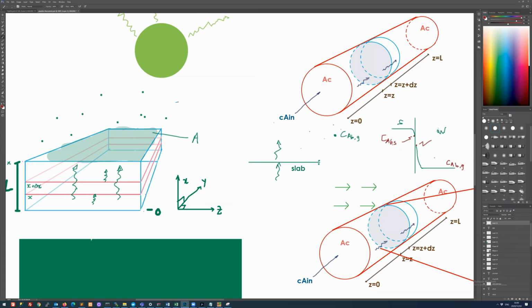And by the way, of course, if your air is well enough mixed, so for example, if you have the slab exposed to a turbulent air stream or something like that, it's going to be well enough mixed that this is going to flatten out. And then you could just use the bulk. You could just look up from the table, from your water table or something, in air under those conditions, what's that concentration? So that would simplify it if the interface value was actually the bulk value of water in air.